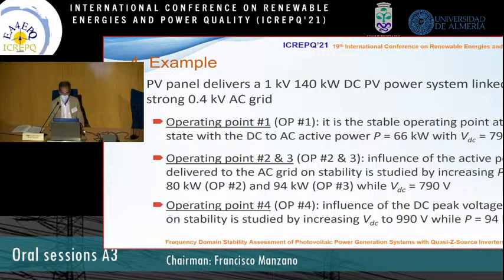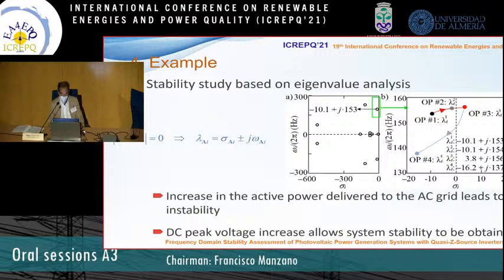First, we study the stability by the eigenvalue analysis. In the slide, we can see the plots of these eigenvalues. On the left, the eigenvalues for the operating point 1, the reference, and we can see that all of them are in the left-hand plane, so the system is stable.